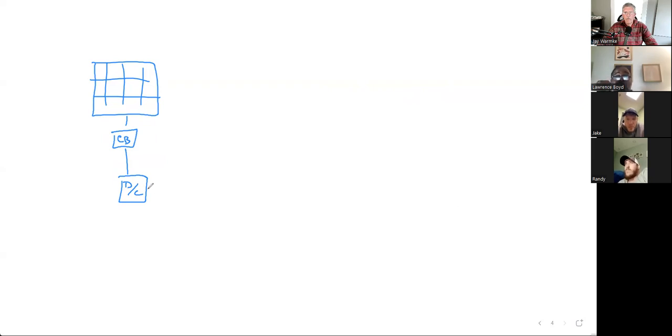Charge controller. No, it's grid tied. We don't have any batteries. Grid tied. Inverter. Yep, straight to the inverter. From the inverter, where do we go? DC disconnect. No, it leaves at AC. So it's going to be an AC disconnect. Okay. Comes in as DC, leaves as AC.